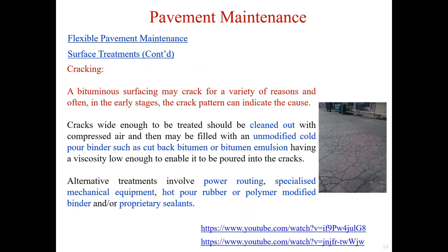Cracking is another common issue, and there are a variety of reasons. Cracks on the pavement surface allow water and incompressibles such as sand, dirt, and other debris to penetrate into the pavement structure. This penetration drastically accelerates the deterioration process.